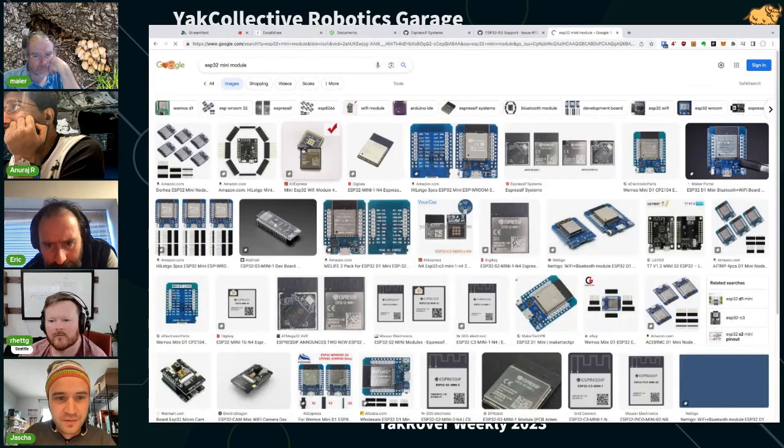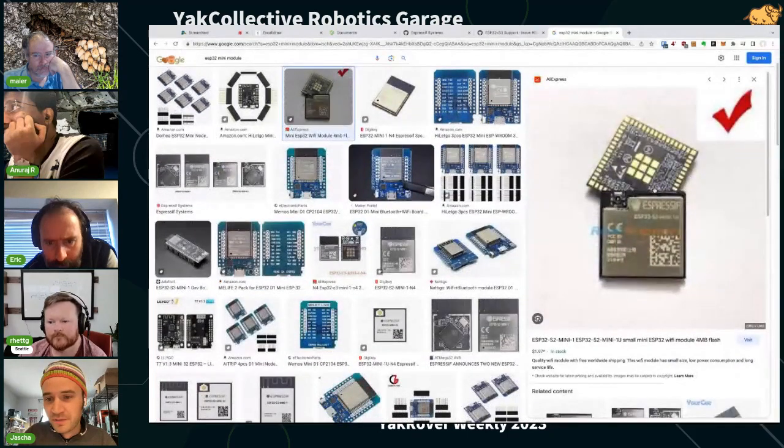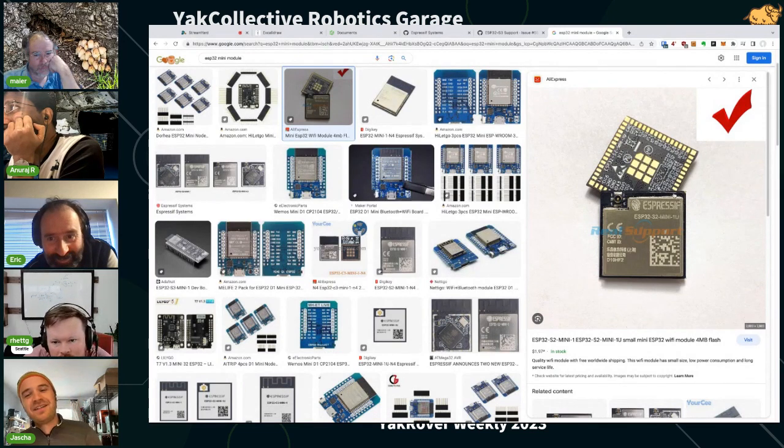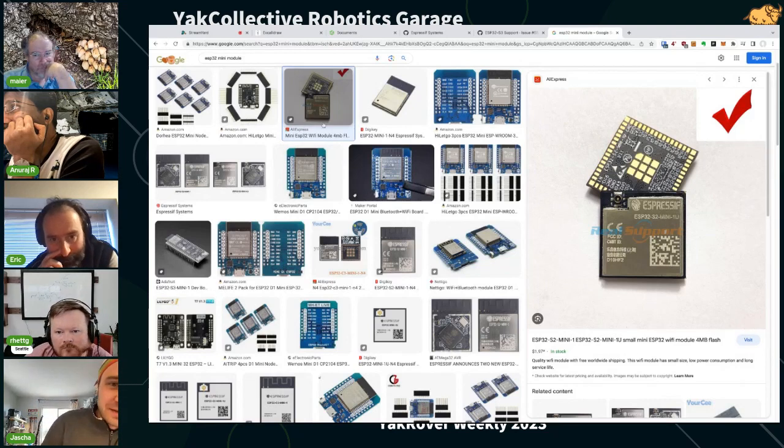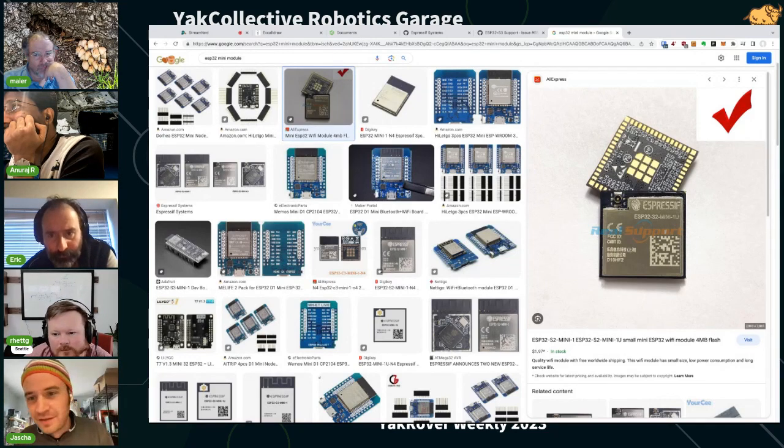Just so you can see. See how the pins are on the bottom side underneath? That is really hard to assemble. And then when there's a defect, when you try to x-ray it, the can is in front of it, so the x-ray gets blocked by the can. These are not worth it for this project.